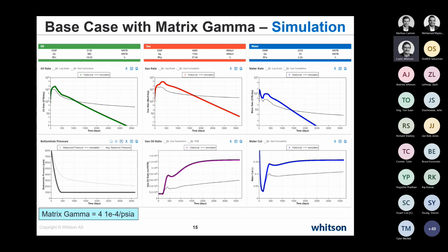And that was one of the things we saw way early on before looking at this kind of thing in gas condensate, CGR variation with drawdown in the Motley, for example, that it could be quite variable. Some of those CGRs could follow exactly the flowing bottom hole pressure tightly, that RV curve, and some lay quite a bit higher than that.